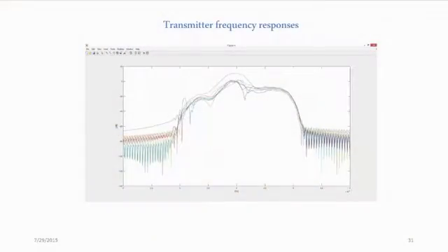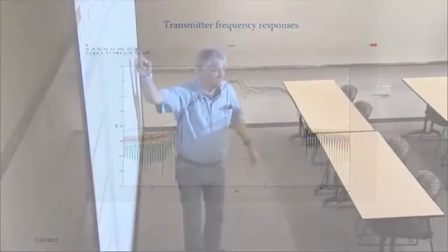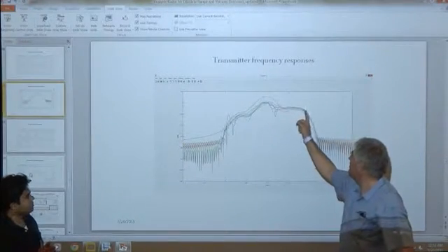So pretty much from what I saw after calibration, your work range is slightly above the resonance frequency, 45 to 50 kilohertz. You equalize the transmitters, and you see the response is flat here. This is your work area. It's not 40 kilohertz, it's here.